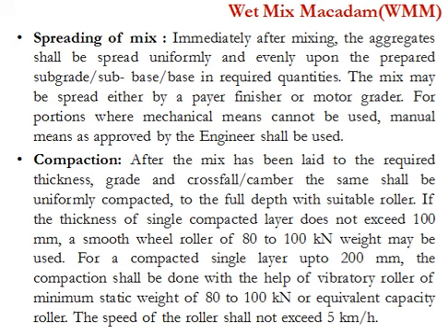or when it causes a wave-like motion. If the level difference or irregularities developed during the rolling exceed 12 mm when tested with a 3 meter straight edge, the surface should be loosened and premixed material added or removed as required before rolling again. In no case shall unmixed material be permitted to take up the depressions.